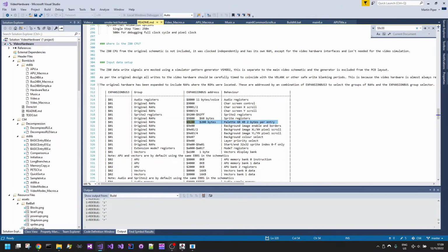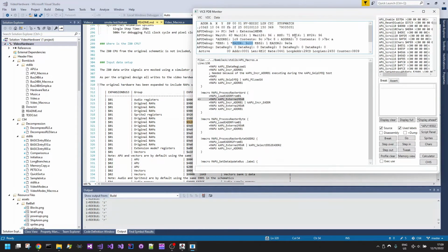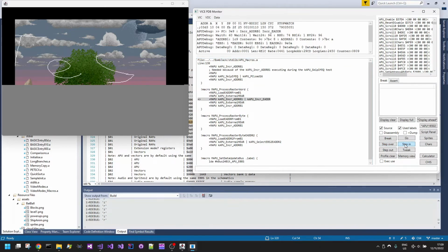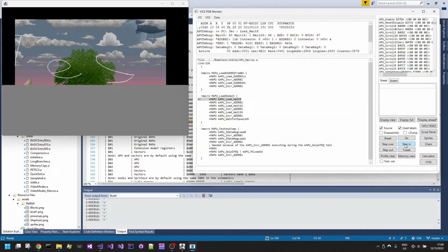So we know that the APU at this particular position on the screen, right here, where the grey area starts, where it hasn't rendered this current frame yet, is actually starting to copy 2 8-bit values, 2 bytes as a word, into the palette. Each palette entry is 2 bytes in size because it's 15 bits of color. So if I keep on stepping here, we can see that it's done a palette write for this position here, and then when it starts to render this next scan line,